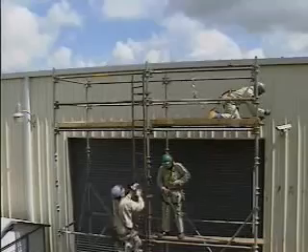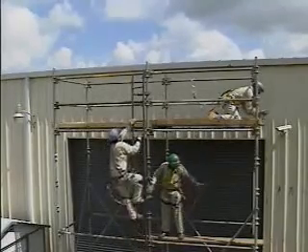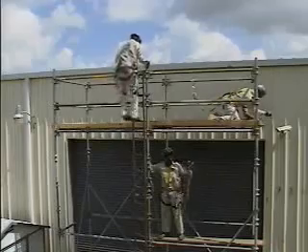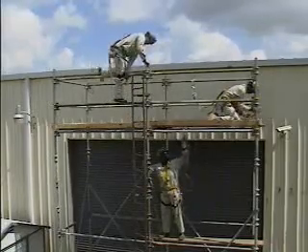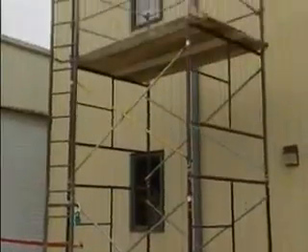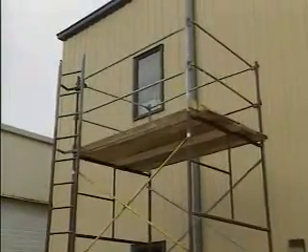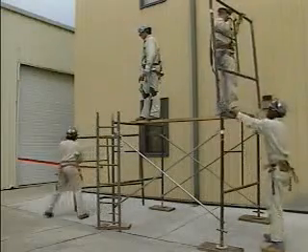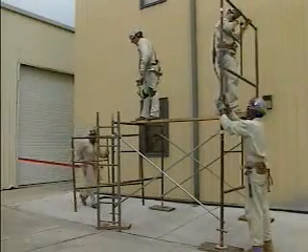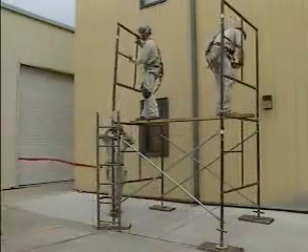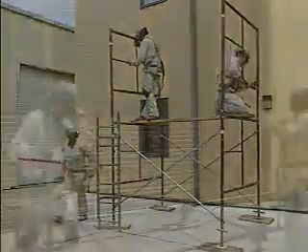A so-called fixed scaffold is basically a temporary elevated steel framework that's assembled on a job site and used to support personnel and materials for construction and maintenance work. A number of different types of fixed scaffolds are available. One type is a tubular welded frame or tubular buck scaffold. It consists basically of prefabricated end sections that are connected with diagonal cross braces.